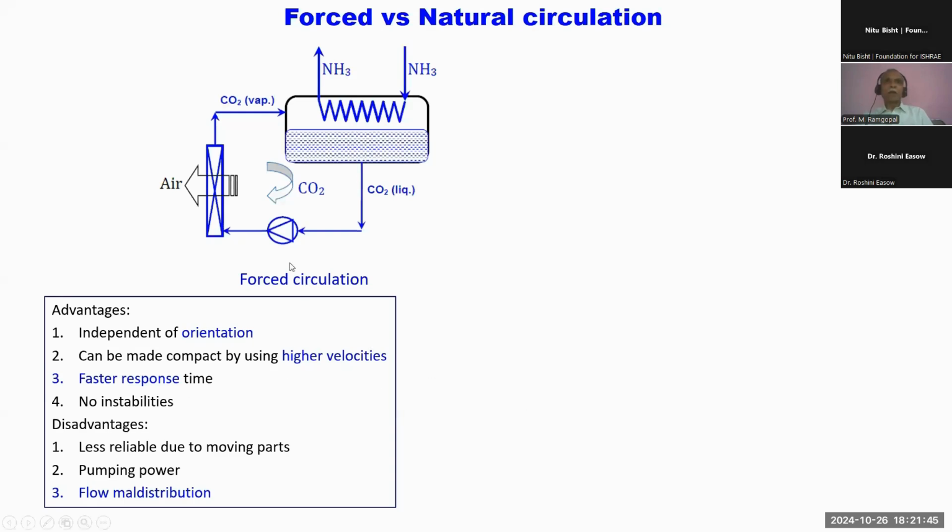The power consumed by the pump will be added to the refrigeration capacity. So this is a loss of refrigeration. In addition, you also have to provide additional power. So this is a disadvantage.